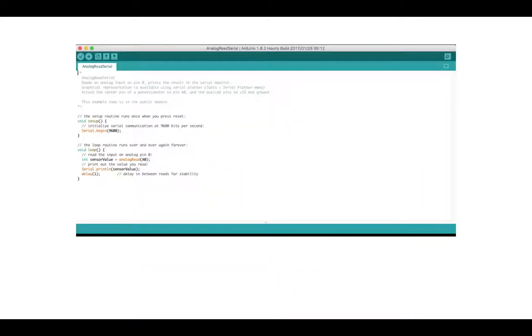All of these are analog pins, and one can use any of these to calculate the random numbers. This is a small program, and it is in fact one of the Arduino examples. The setup function just configures the speed, which is 9600, between the Arduino and the serial monitor of the computer.